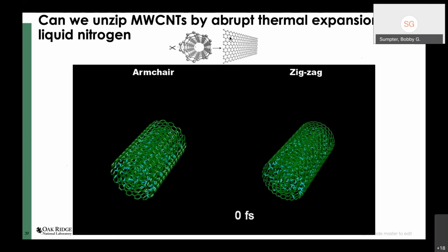And to make a device, you need semiconducting properties, not the metallic properties. So controlling the width of graphene is very important, yet very difficult to do, because when you do the chemical synthesis, you get a statistical average of different widths, and that won't work for an actual device. You need a single width.